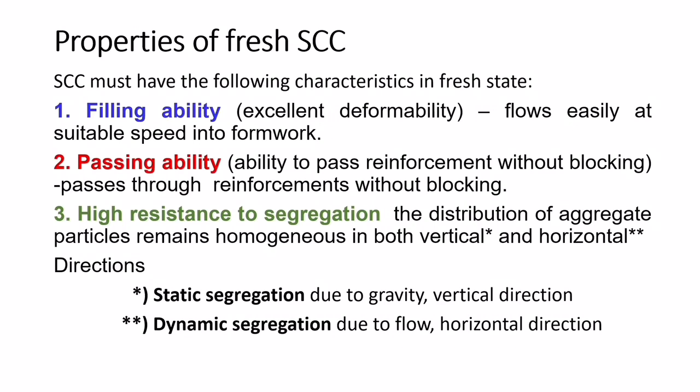High resistance to segregation: the distribution of aggregate particles remains homogeneous in both vertical and horizontal directions. For vertical direction, static segregation is due to gravity, and for horizontal direction, dynamic segregation is due to flow.